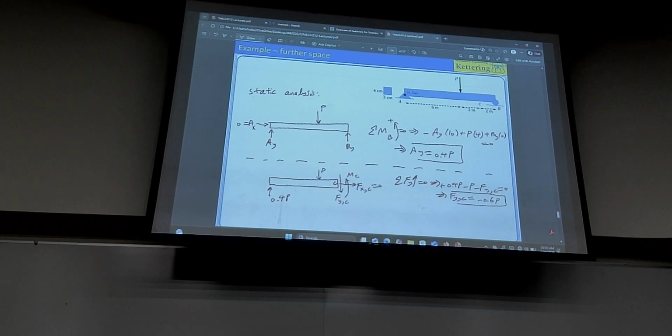Sum of moments. Now, about which point? Point C. It makes sense. In fact, it could be any other point, but C happens to be easier. So let's do that: sum moment about C. Help me, start from left to right, please. Moment of this about C. First, is it positive or negative? Pin at C, flick it with that force, visualize. Clockwise or counter? Clockwise.